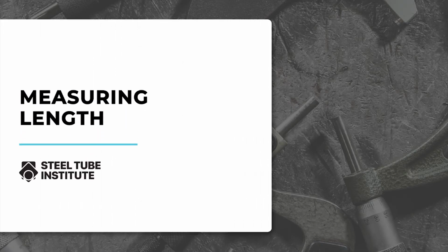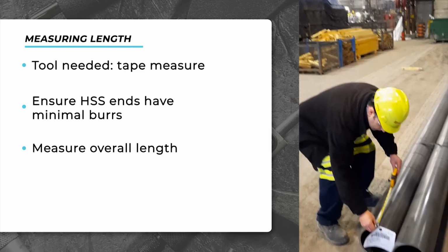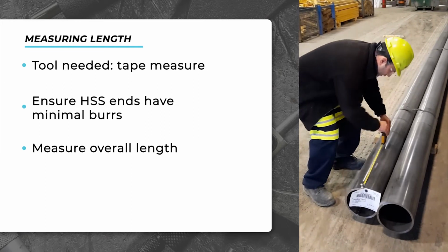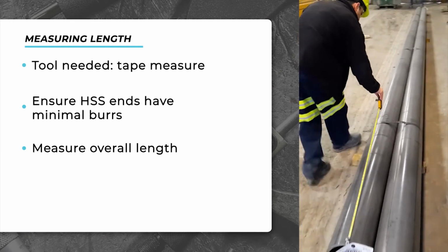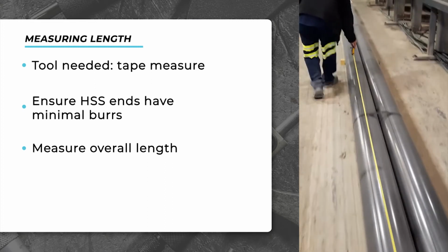This video will demonstrate the length measurement. For the round HSS bundle that you will see, we want to make sure the ends of HSS have minimal burrs. All we will need for this measurement is a tape measure. We can go ahead and pull our tape tight to measure the overall length.